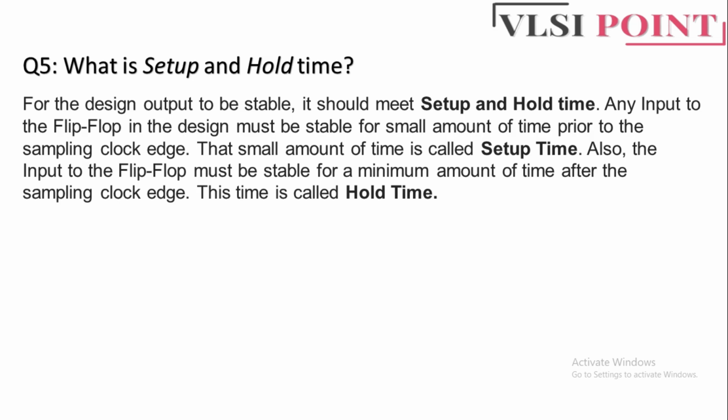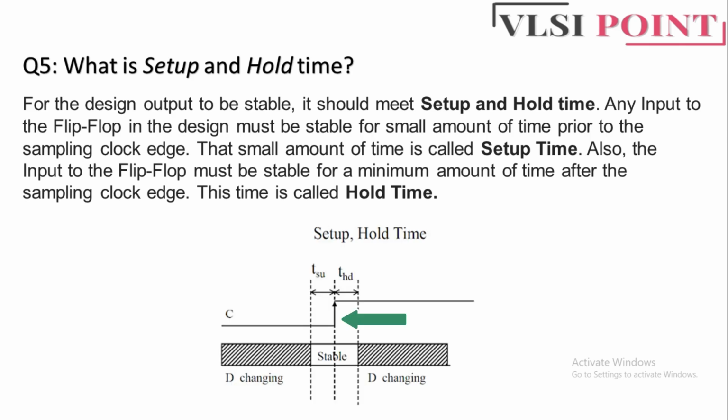The hold time refers to the minimum amount of time that the data signal must be stable and valid after the clock signals arrive. You can see here in this figure, this is the time where the clock is coming. This is the time before the clock signal when the input signal should be stable. This time is called the setup time, and this is the time after the clock arrival. This is called the hold time.